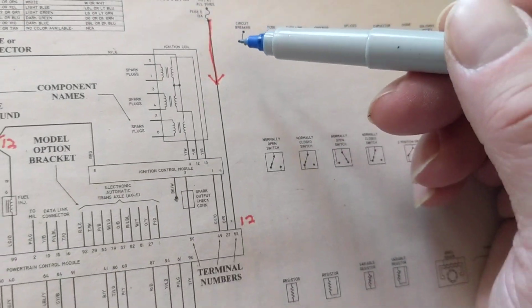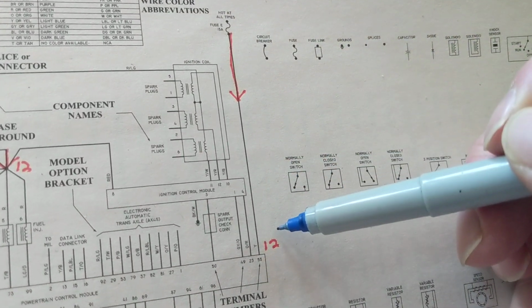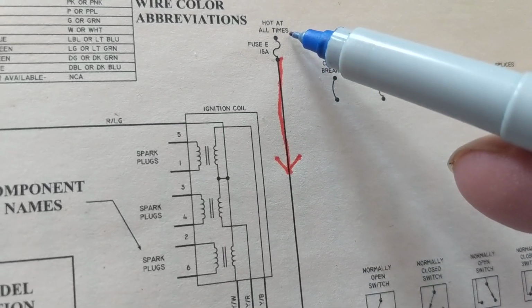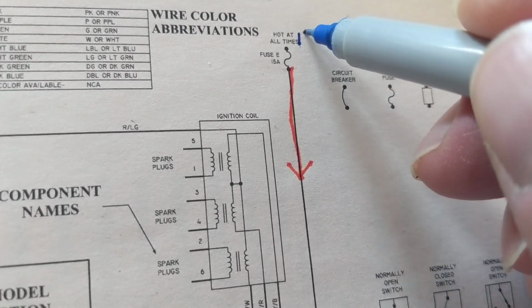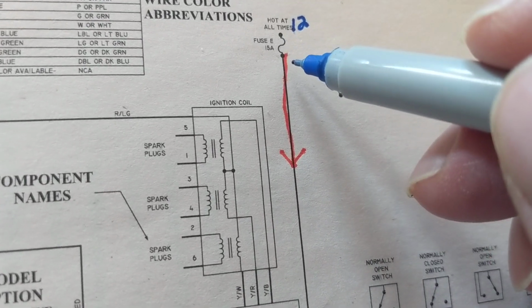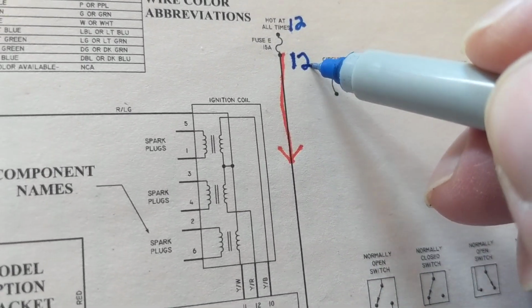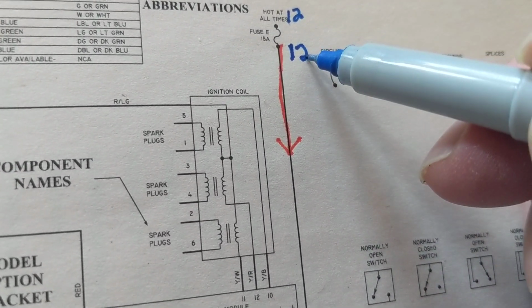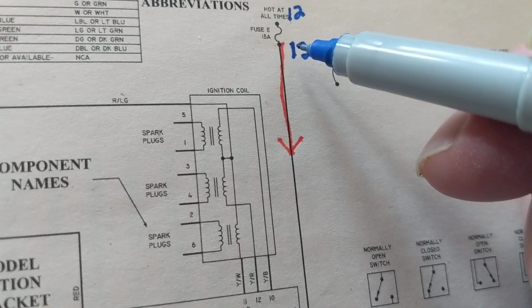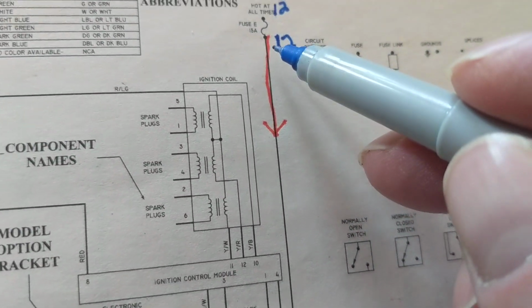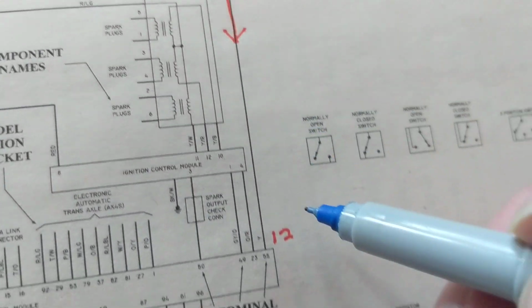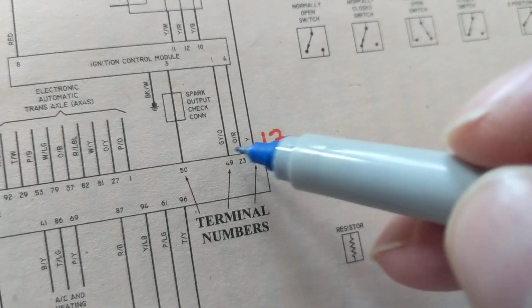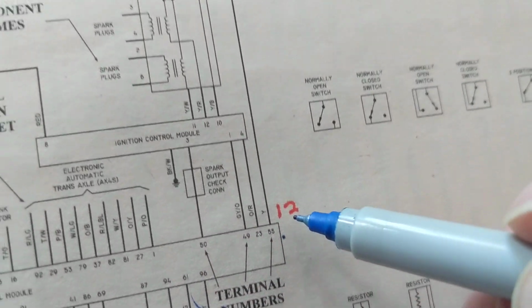Now, we find where the main point is going to 12 volts. If we come over here, hot at all times, this fuse will always have 12 volts. So let's draw it in. One side. After the fuse, how much should I have? 12 volts. Does it make a difference if it's 15 amps or 30 amps? No. So if I have 12 volts here, 12 volts over here, how much voltage did I lose across this? 0 volts. Now, the flow is through here, the current flow, and guess where we are? So we landed at pin, what? 55 of the PCM control module, getting 12 volts.